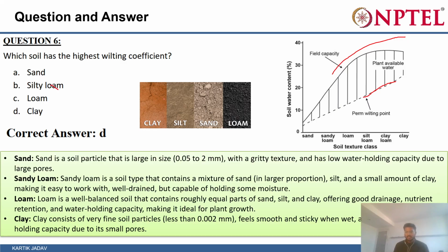For sandy soil, there is low water availability due to higher pore space, or larger particle size, so quick drainage happens there even if water is available. So the wilting point and field capacity, or total available water, for sandy soil is too low. So our first option is ruled out.